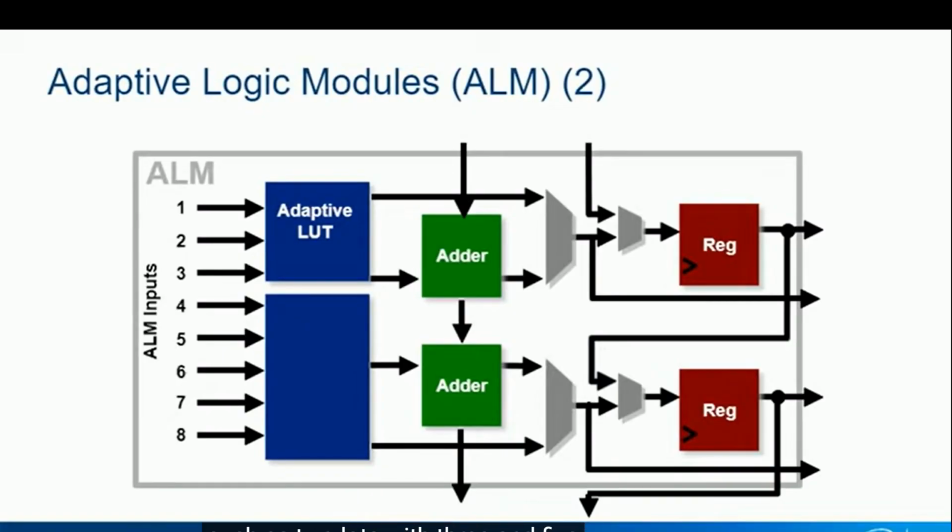An ALUT can also be split to support a more complicated 7-input function with the extra input used for register packing. Splitting into 4-input LUTs makes the ALUT backwards compatible with 4-input LUT technology found in standard LEs. Finally, some other splits are possible if inputs can be shared between 2 functions. ALM-based FPGAs provide extremely high-performance logic operations using fewer resources and smart resource management.